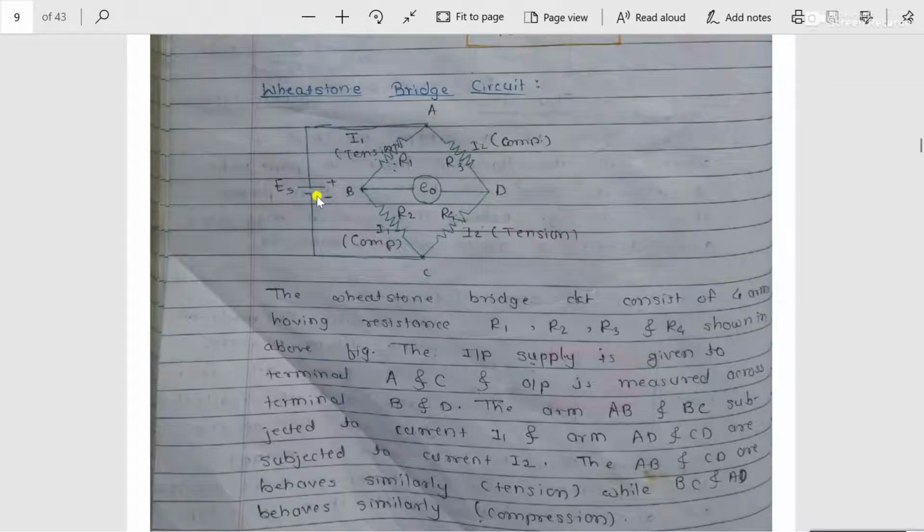If I have to use four strain gauges, then instead of providing constant resistances, I have to provide the four strain gauges, and by using those 1, 2 or 4 strain gauges, I have to check their change in resistance value, and those changes in resistance values are useful for further calculation.